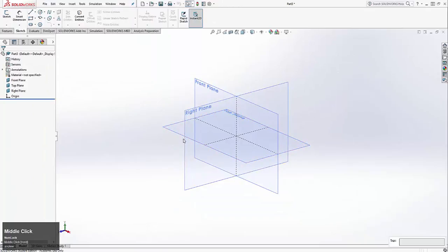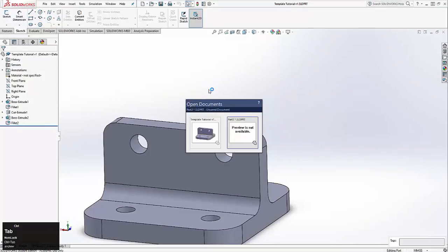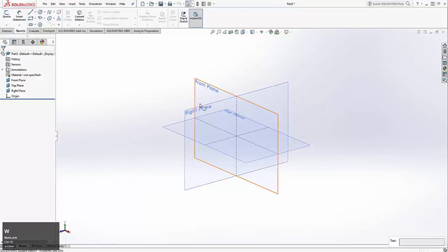And another thing to note is that SolidWorks can have multiple windows open. So actually, if I go back and open the file I just closed, it can be useful to Control Tab, which allows you to go between the two windows. But I'm going to just close that. And if you have a lot of stuff open, it's going to start slowing SolidWorks down because it takes all of the open files and puts them into memory. And you don't really need to worry about necessarily what that means, other than if you have a lot of really big stuff, it's going to start slowing down your computer, and SolidWorks isn't going to be happy.